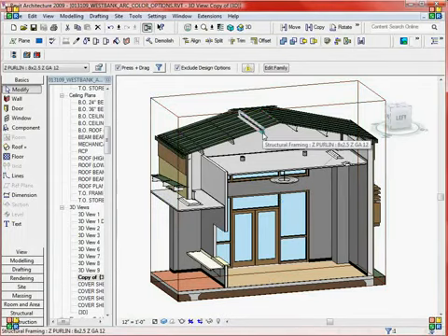These purlins are families that we created, and it's created one time. So in any successive projects after this, if the purlin has to change in size, all we have to do is key in the dimension, and that three-dimensional purlin automatically changes.